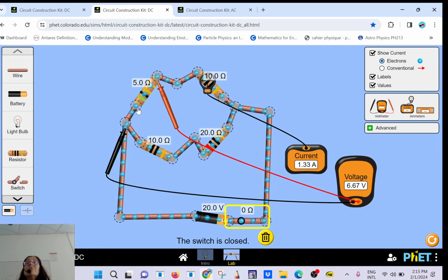It works the same here for current. You see the peak value is what? 1 volt. So the RMS will be 0.7 volt. Very good. Okay. And why do we need those RMS values? It's because we can use Ohm's law. V equals Ri will hold for an AC circuit only if you are using RMS.